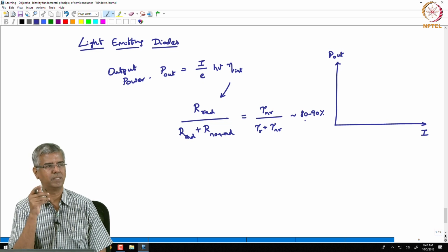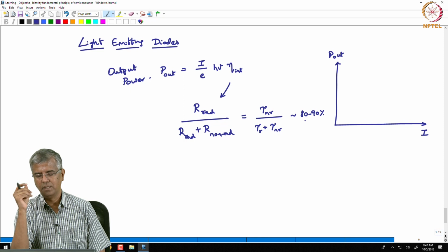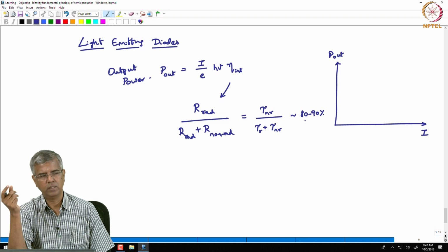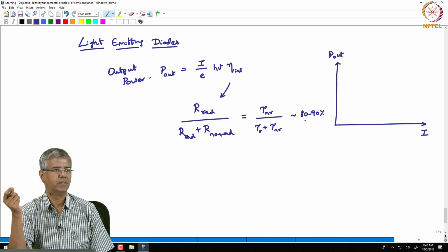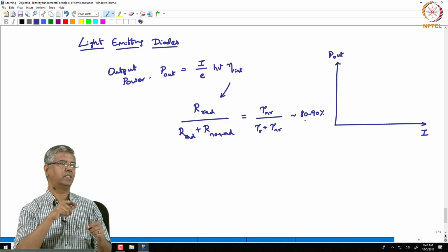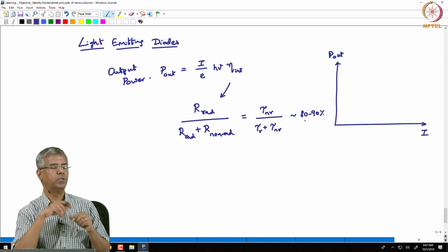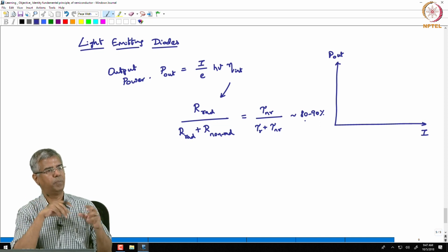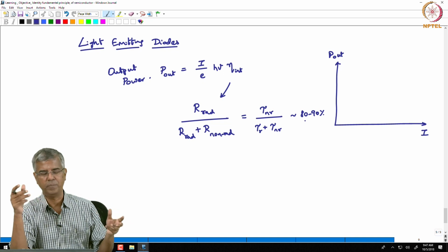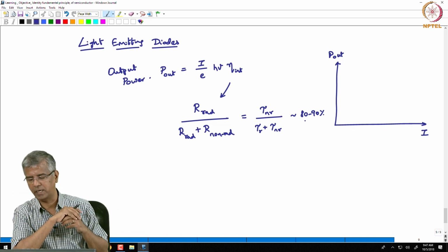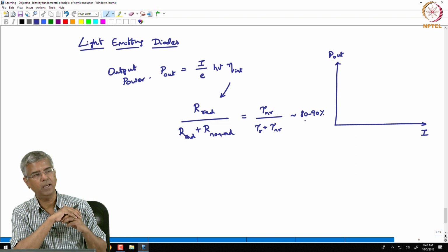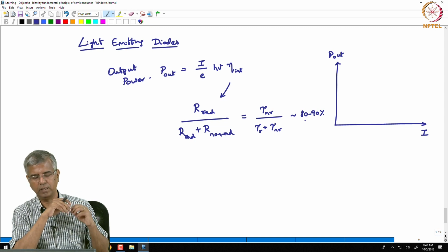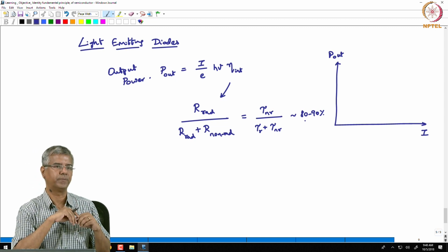In silicon, the story is different. We understand that it is an indirect band gap semiconductor, so there is no direct recombination happening. That recombination would have to be associated with typically a phonon or a vibrational mode that takes out that extra change in k, the momentum, and that means your eta int is much lower.